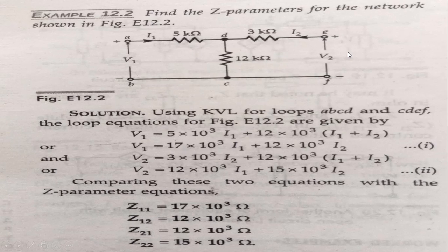Similarly, go for the V2, because you look from the output side. If you are observing from the output side, what will be the effect of that? So again, V equals IR, plus again V equals IR. Here through the 3K, I2 is going to flow, and in the 12K, the Z2 as well as the Z3, or in short, the current I1 is flowing, because here it is I1 plus I2, here I2. So you just segregate which current is flowing and make an equation.